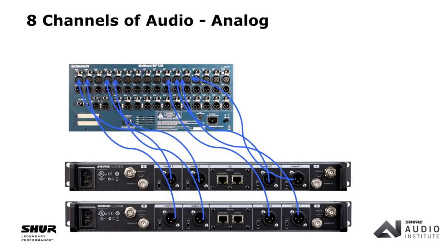One of the main ways it's utilized now is in something referred to as networked digital audio, or sometimes called audio over IP or audio over Ethernet. It's a networked protocol that allows you to essentially multiplex many channels of audio onto a single Cat5 cable, for example.